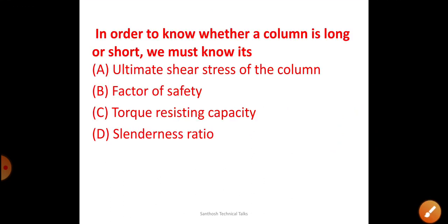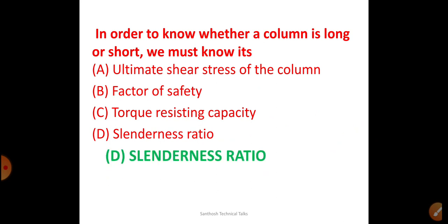And the next question is, in order to know whether the column is long or short, we must know the slenderness ratio. The slenderness ratio is very, very important. Based on the slenderness ratio, we classify a column as either a long column or a short column.